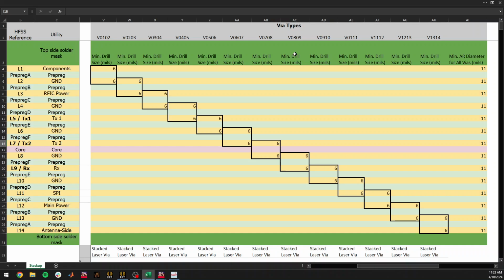And what that lets you do is essentially create these 2-layer vias that can go in any section of your PCB, and you're not having to rely on a through via, or you can essentially realize any sort of buried via or blind via or through via if you want, and you do not need to incorporate back drills into your design. And back drills, sometimes they're useful. It definitely helps you realize a cheaper design, or cheaper via type, but they do have some impact on your performance. But that's not the topic of this video.